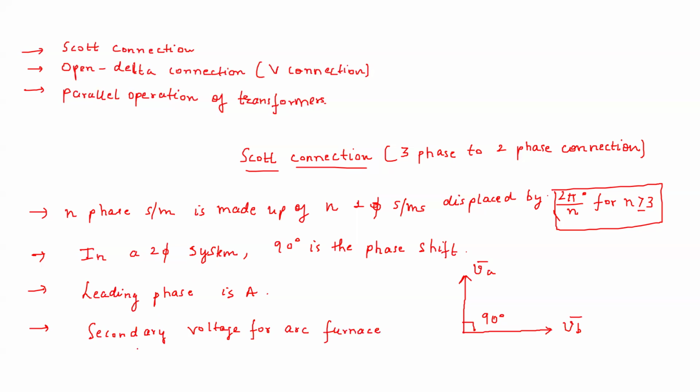You will see in the questions also that they will say that in the Scott connection, on the three-phase side you're giving the supply, and on the two-phase side you have an arc furnace. So this is the application of a two-phase system.